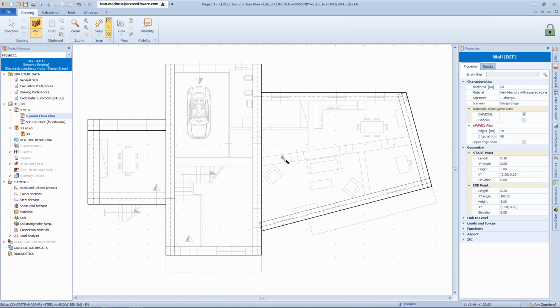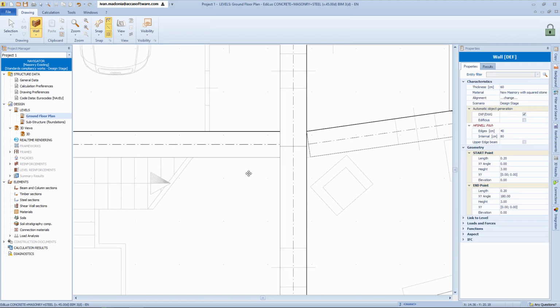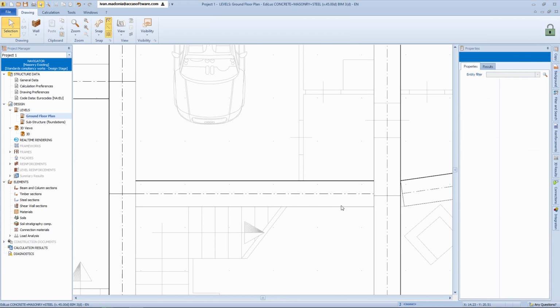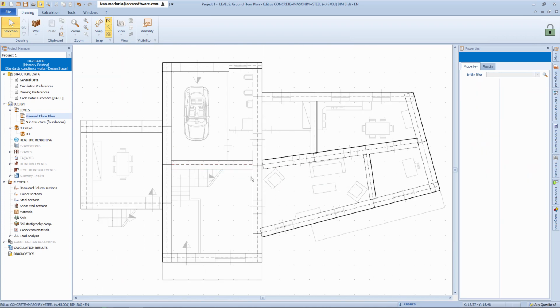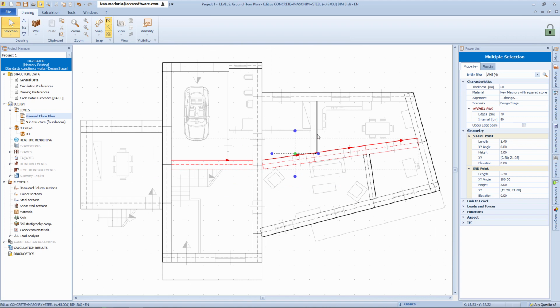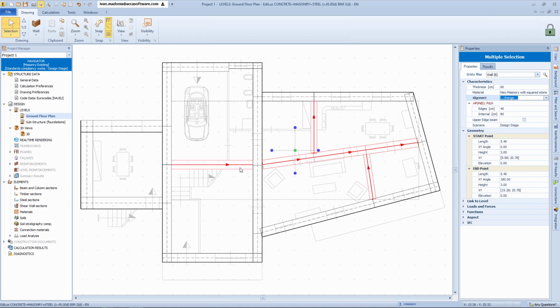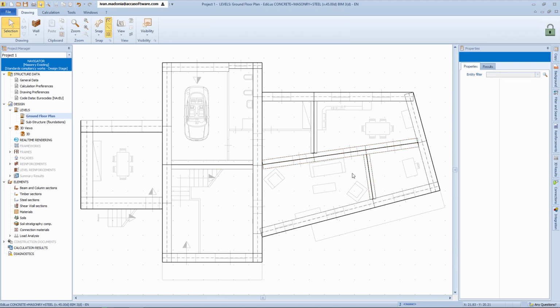When designing walls, we can notice a construction line with a greater thickness. This indicates a fixed line. For example, if we copy this wall to other levels, the reference will be the line with the greatest thickness. You can also change this alignment. For this you just need to select the desired elements, and in the right side properties panel, we find the alignment option. In this way we can change the alignments of the selected walls, so that in a repetition of these walls that can be performed in the upper floors it will be done with a center alignment.